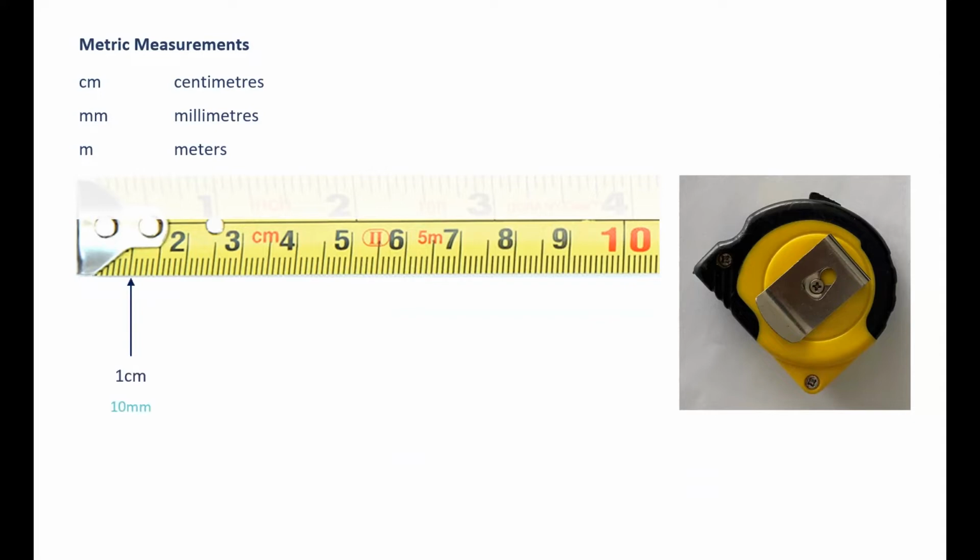So you can see here on the tape measure, ignore the top numbers, the bigger numbers, the imperial measurements, and we just read from the smaller numbers. So there's 1 centimetre here. This kind of takes it right to the edge. You can't always see the 1 actually. Then we've got 2 centimetres, which is also 20 millimetres.